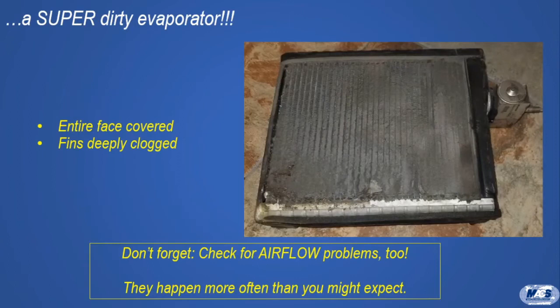The evaporator core was caked in mud and more debris. It was a bit messy to clean it out with brushwork and soapy water, but that dealt with the issue, and it was a lot less onerous than pulling the dashboard. The truck was used on construction sites, so this really should not have been a surprise.